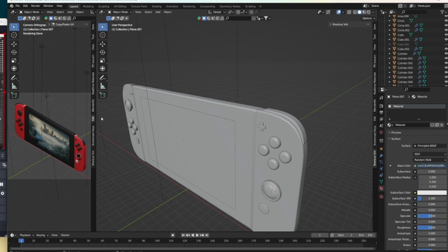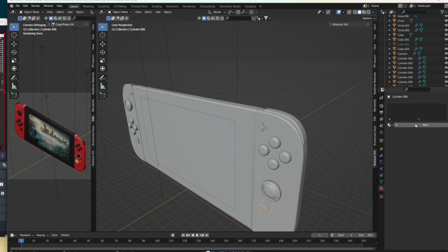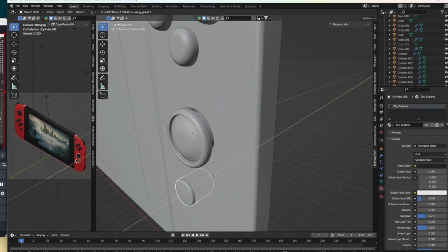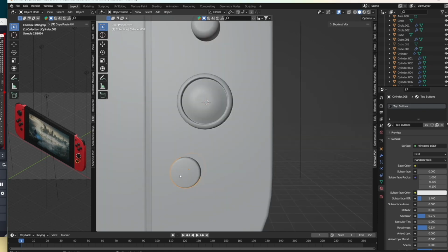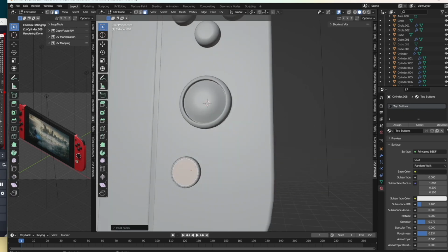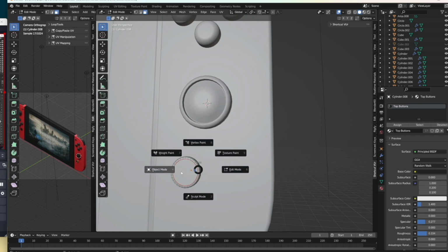So that basically took us a small amount of time, and so far so good. It looks really lovely. Now our home button will be black as well. It looks like with our home button, we can probably extrude it a little bit more forward. Before we can add an icon to this object, we need to tab in, select the face. We want to inset the face just a little bit, and then we can actually just separate this face. So P for separate, and we separate this face.